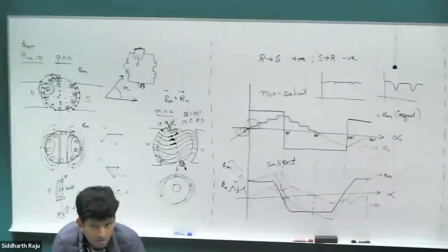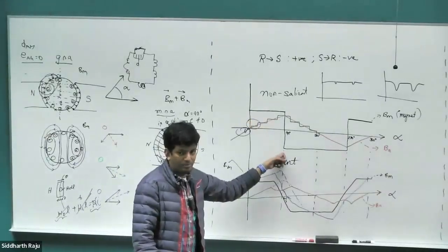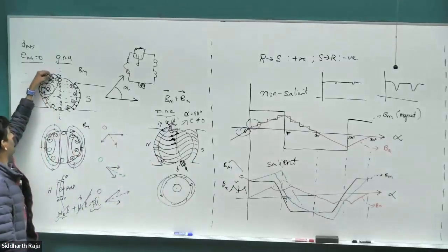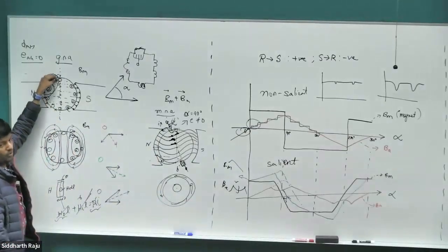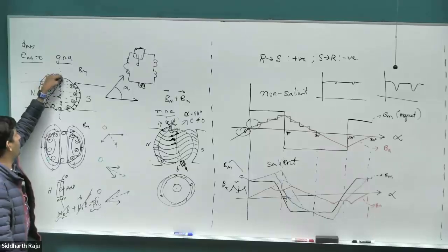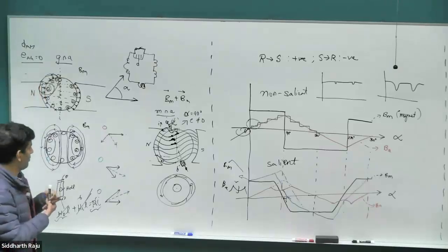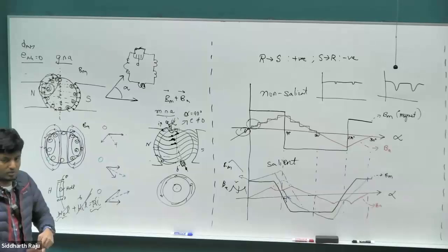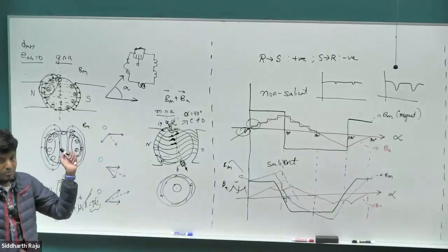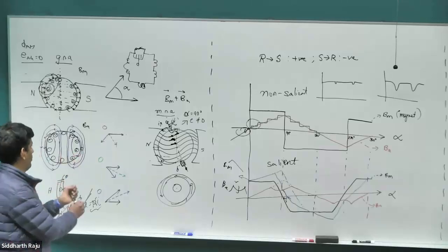I'm still a bit confused about the BM completely flipping like that. I guess I'm just confused about the rotor to stator convention. What exactly is the point or line where you define it? If the field lines go from the stator to the rotor, I'm going to use the convention negative. If the field lines go from the rotor to the stator, I'm going to use the convention positive. But is it the entire surface of the rotor and stator? No, that would be the flux. I'm talking about the B field, at every single point, right? The vector direction of the B field.